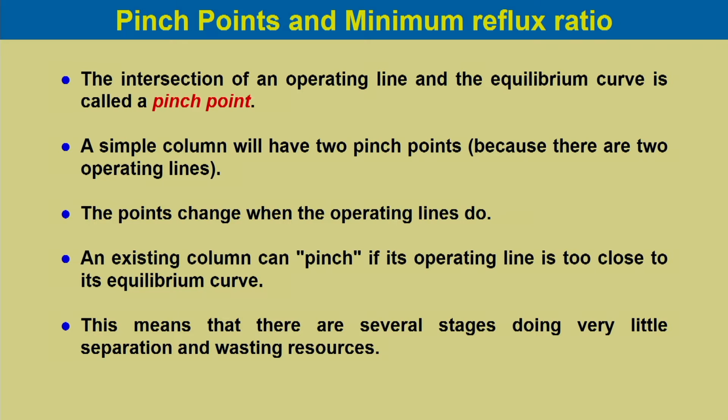That means, as the gap between the operating line and the equilibrium line becomes very small, the number of stages required will increase gradually as the distance decreases, and at the pinch point you will see that the driving force is very small to make an effect on the separation performance. So, we will need a large number of trays or stages for a given separation. So, that will waste our resources if we run the column very close to the pinch point condition.